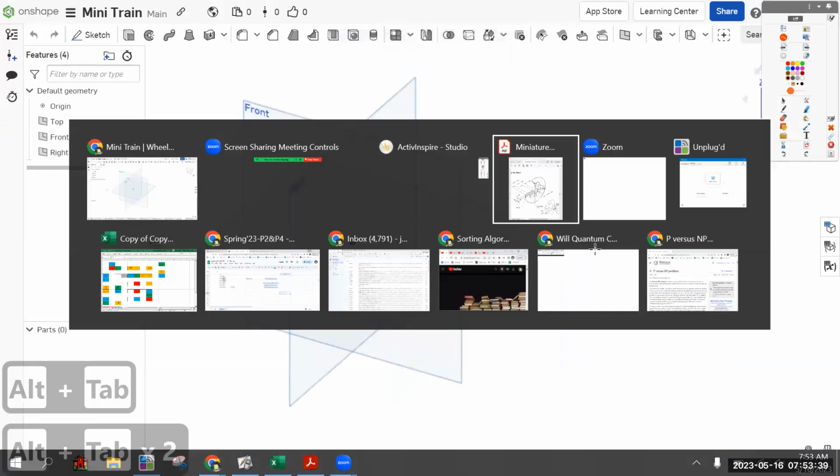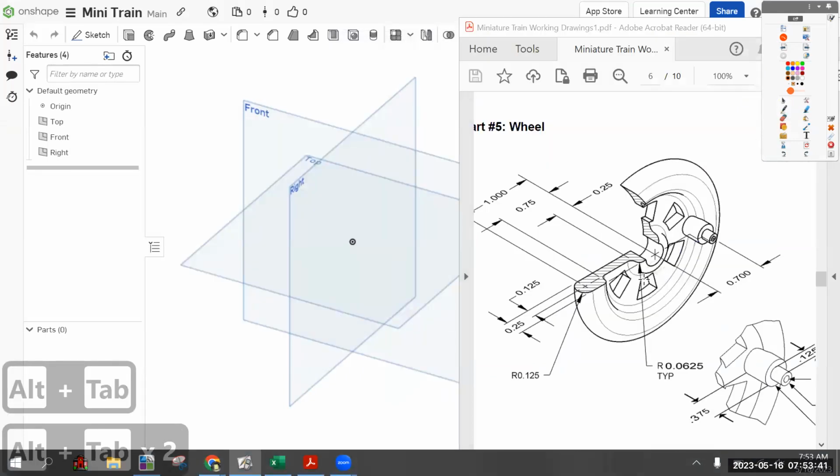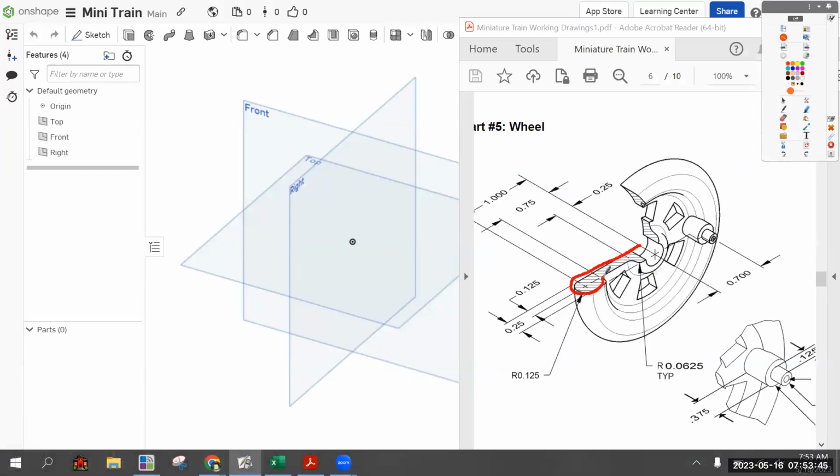So there's this main sketch that's going to be our sketch for the revolve. But you'll notice that our center axis, which goes right through the center of the wheel, there's no material there. There's no material right away. And that's what makes a hole in the middle. The first material starts, and we don't even have a dimension for that.